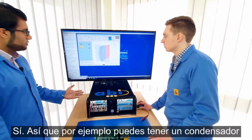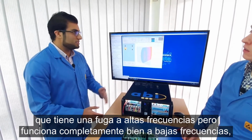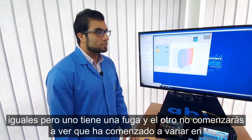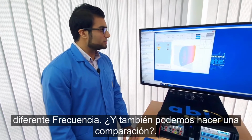Yeah. So for example, we may have a capacitor that's leaky at high frequencies, but it's completely fine at low frequencies. This could show us the variation. Exactly. So if you're comparing two exactly the same capacitors, but one's leaking, one's not, you'll start to see it start to vary at different frequency. Okay, and we can also do a comparison?